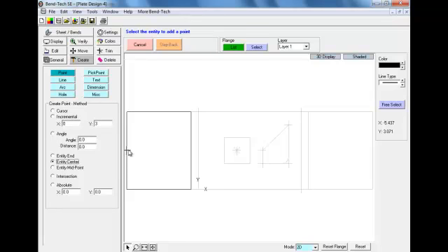We're first going to select our left flange to start out. Once we have that selected, we need to place a hole to create our hole feature. So we will select Point, hit our Entity Center. We're going to use that to define our first point in this flange.